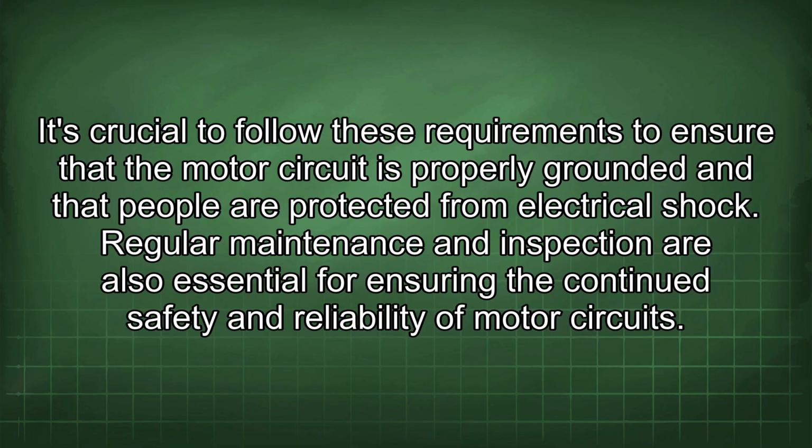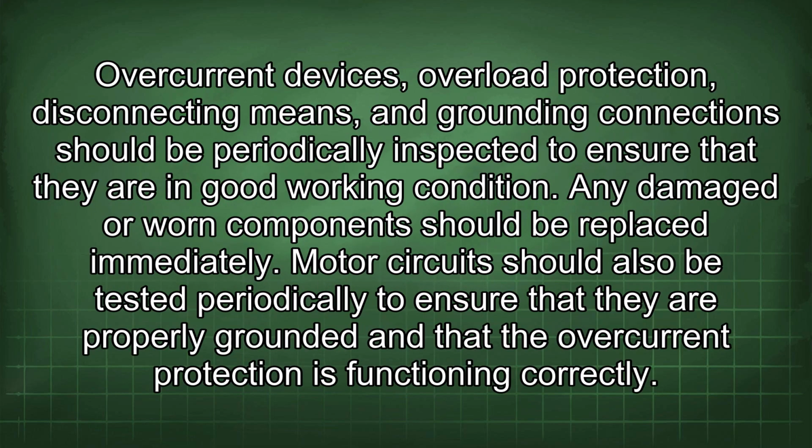It's crucial to follow these requirements to ensure that the motor circuit is properly grounded and that people are protected from electrical shock. Regular maintenance and inspection are also essential for ensuring the continued safety and reliability of motor circuits. Overcurrent devices, overload protection, disconnecting means, and grounding connections should be periodically inspected to ensure that they are in good working condition. Any damaged or worn components should be replaced immediately.